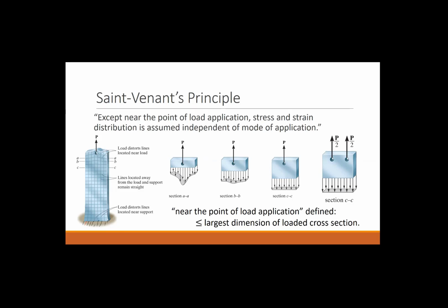Or, let me rephrase. St. Venant's principle tells us that if we look far enough away from the point of application, any stress state that we look at will, as long as it has the same sum of forces, be representative of that loading.